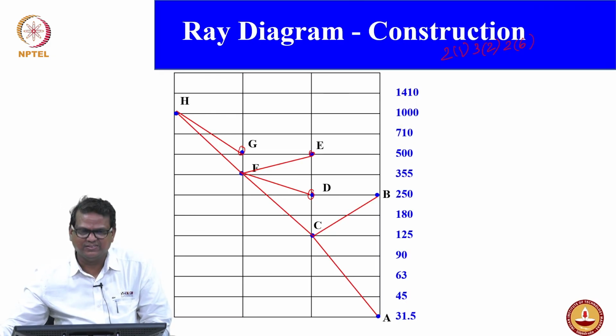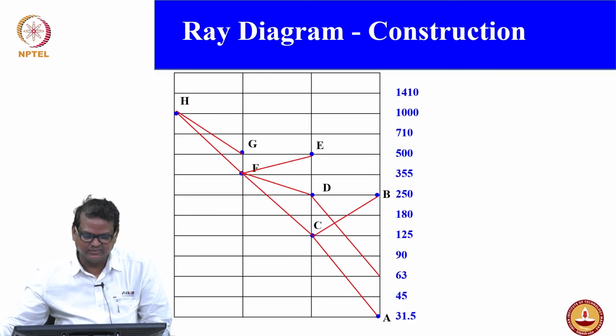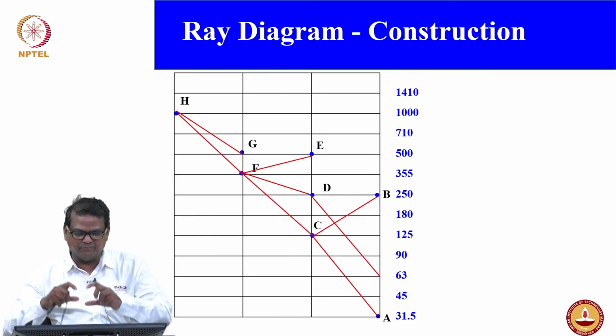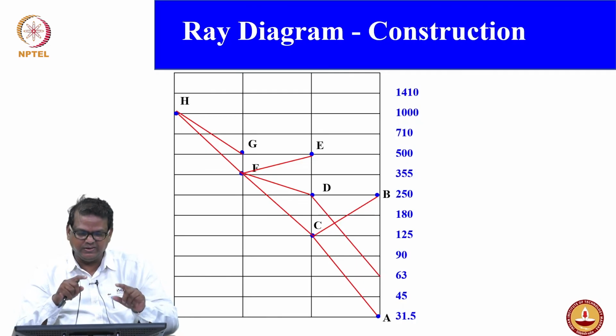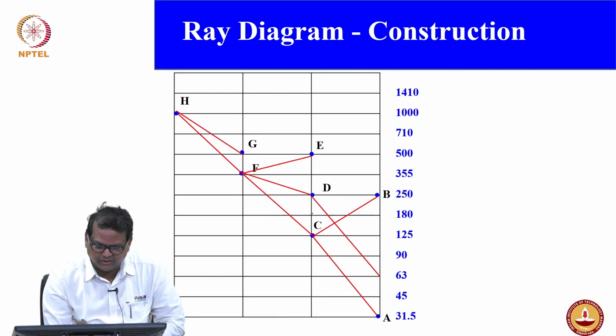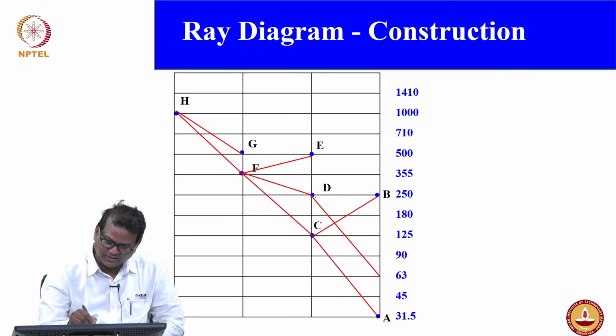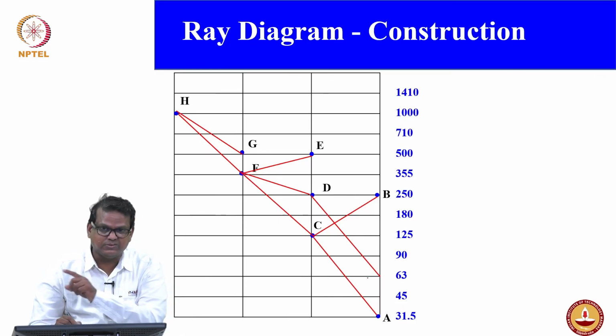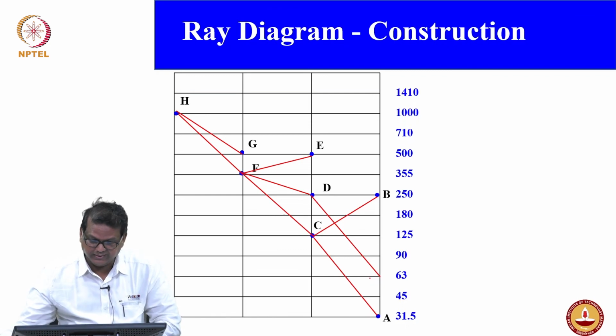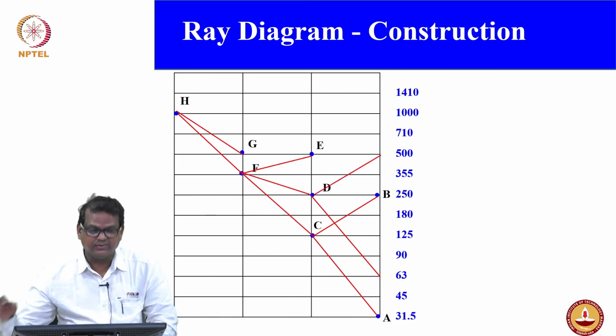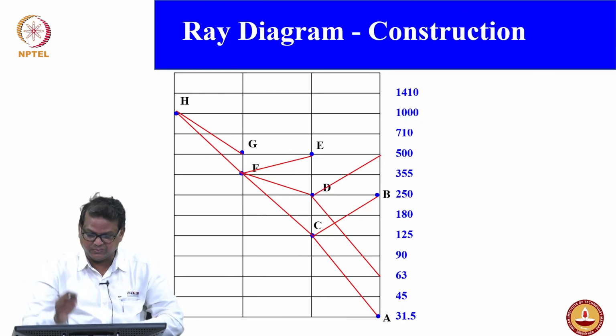Look at this. I am drawing parallel lines because I am following the step ratio. So, look at this, this is 250 rpm, this is 125, fine. The output has to be 63 in stage 3, again with a 6 step difference.